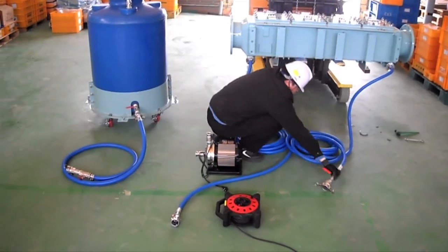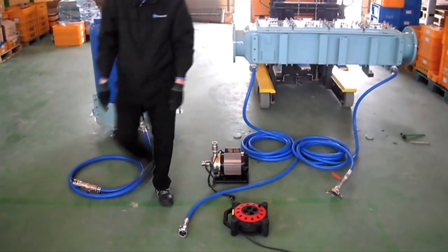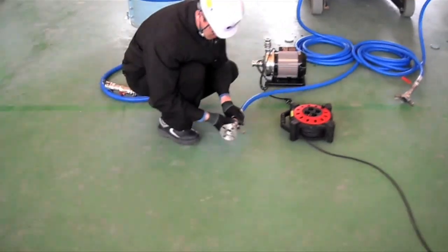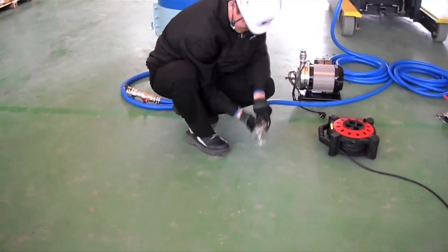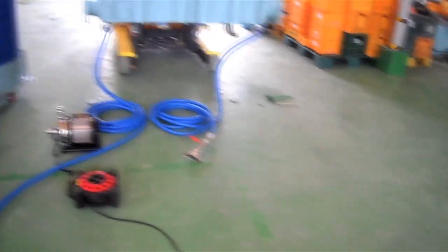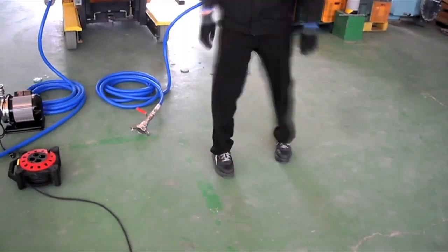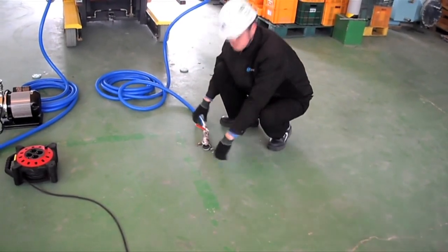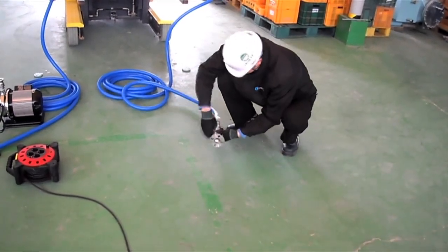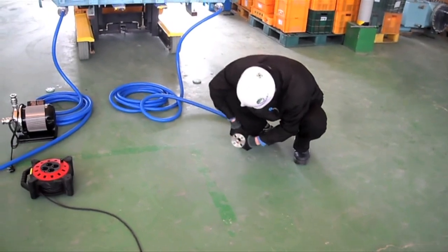Drain seawater from chamber through drain D1, D2 of ECU. 4. Inject cleaning agent with fresh water. Please refer to Table 1 below for the appropriate amount of cleaning agent and fresh water. 5. Disconnect the fresh water pipe from tank T2.